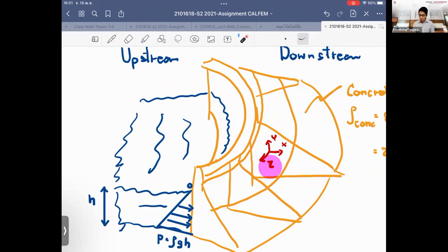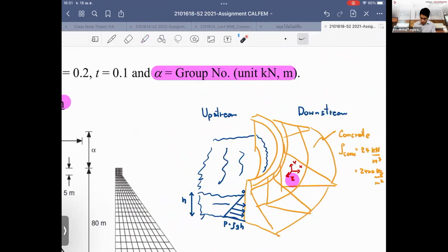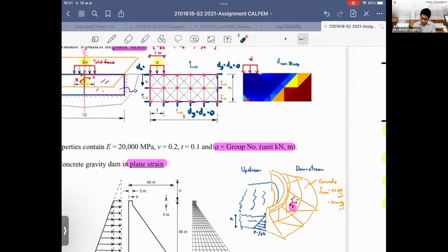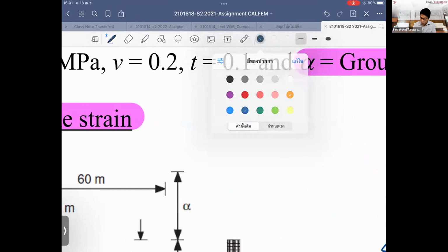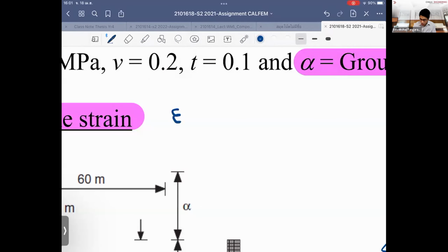The strain in the radial direction, or the direction perpendicular to the plane of every slice we cut through, doesn't exist, because it is so thick. That's why we can simply model this problem as plane strain, by saying that the strain in the direction perpendicular to the cut of the slice we're looking at in the plane, including the shear strain as well, equals 0.